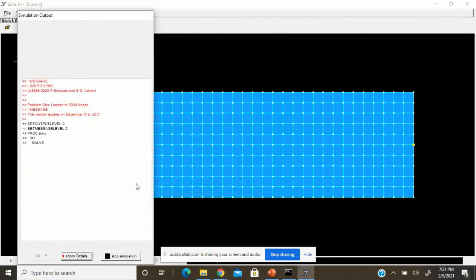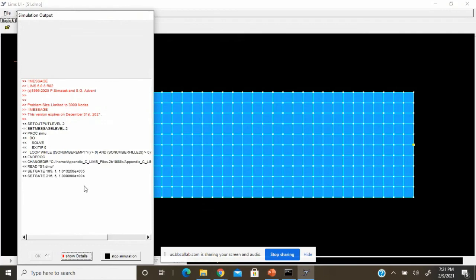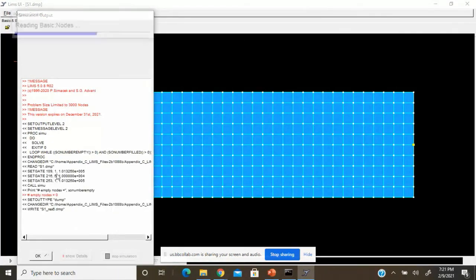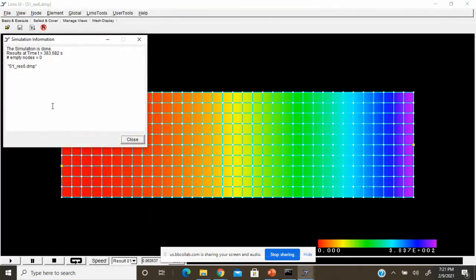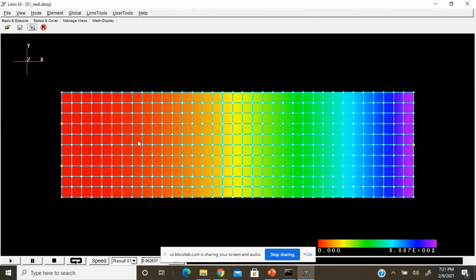And once I start to run, you can see here the gate has been set as venting, and you can see how the rest of the other two inlets are set as the injection ports with a higher pressure. So once I set OK, you see that the time taken for the complete fill to happen is around 383 seconds.